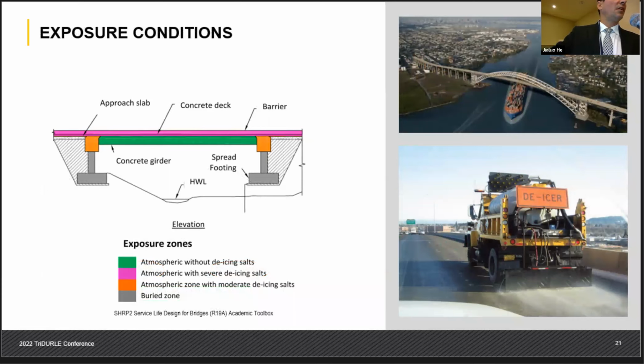The bridge deck, the substructures, the foundations, all of them are going to have different conditions. Some of them are going to be submerged, some of them are going to be partially submerged, some of them are going to be exposed to the chemicals directly, some of them are going to be splashed, some of them are going to be airborne. All of them are different conditions you need to consider.